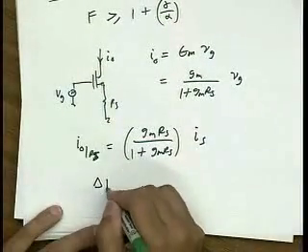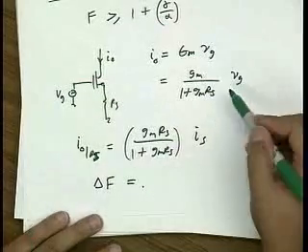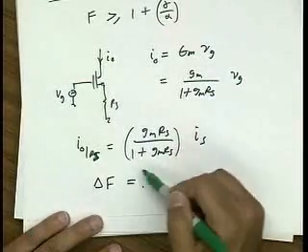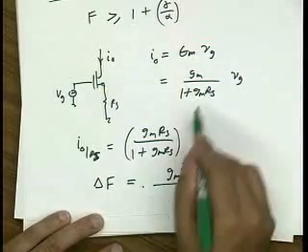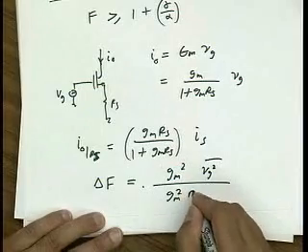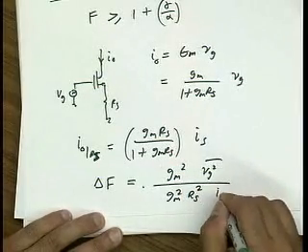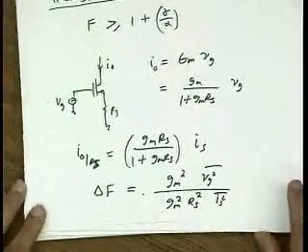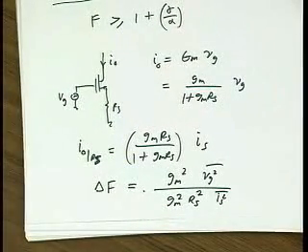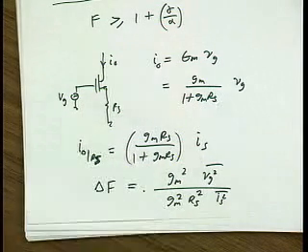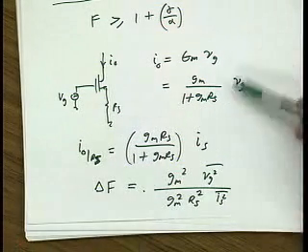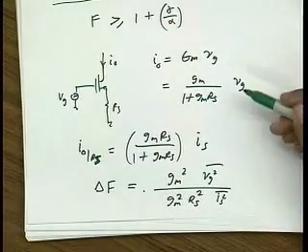Then the fractional noise figure is this noise divided by this noise. So it's Gm squared V gate squared, the denominator is the same so it goes away, divided by Gm squared RS squared IS. Let me make sure everybody understands that. Questions? Is this at low frequency? Yeah, we're still assuming that we're at moderate frequencies where we've obviously neglected the effects of CGS.